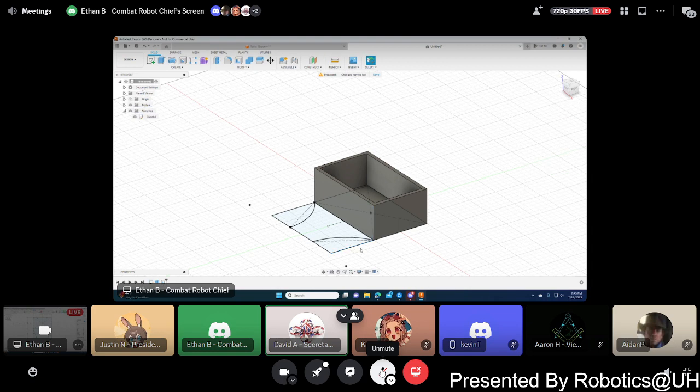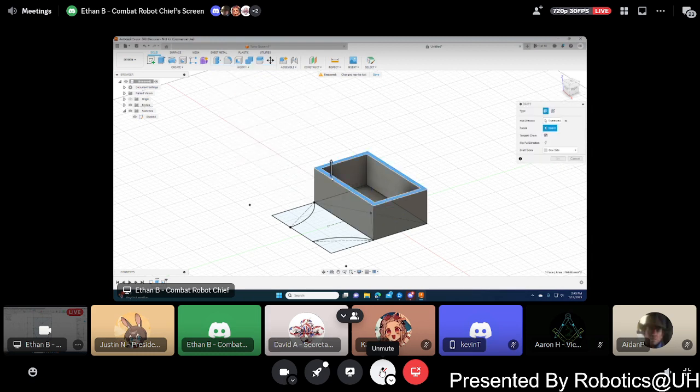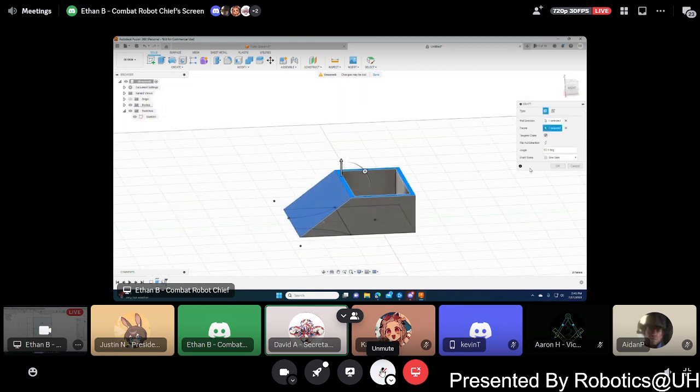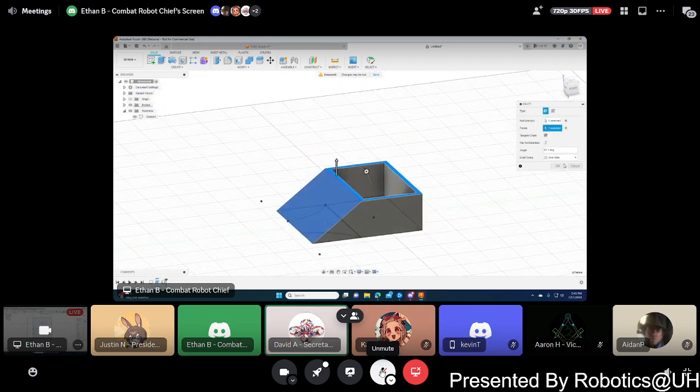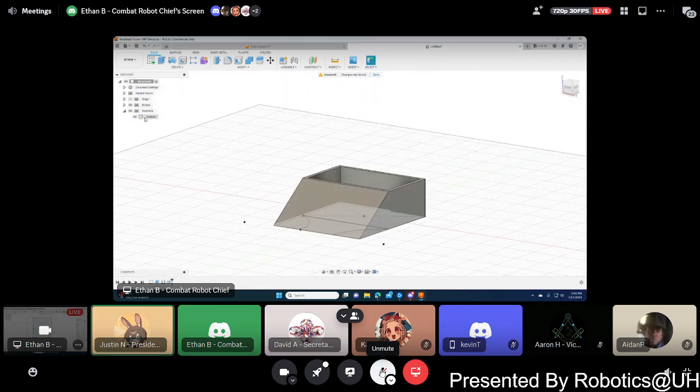Can you continue? There's another good reason to use constraints, because if you don't constrain it, then the sketch can move once you make modifications to it. And if it moves out of alignment with an intersection, then you can't apply 3D modeling to your sketch. Yes.